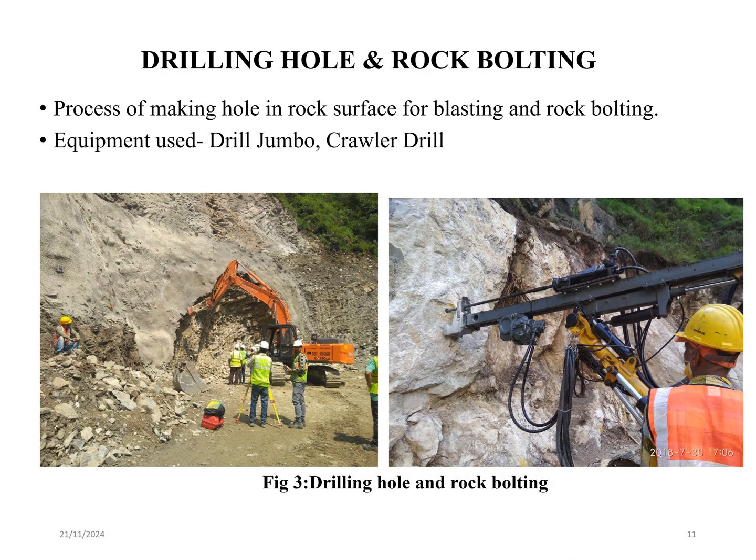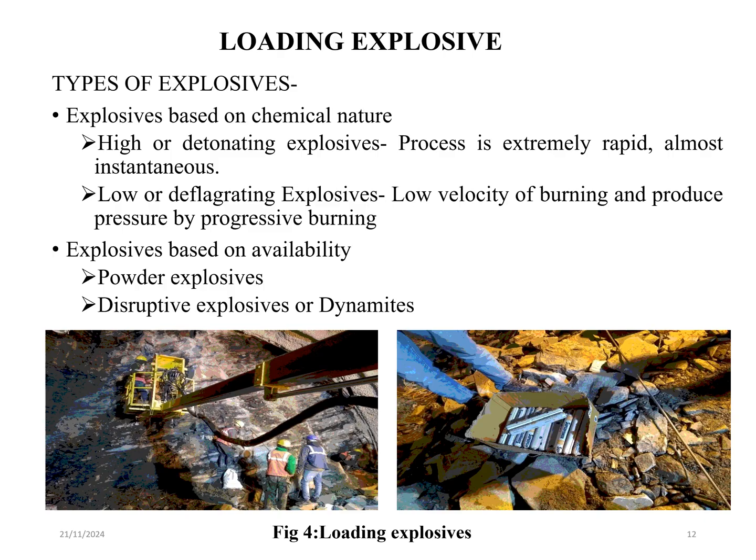Drilling holes and rock bolting. This step involves making holes in the rock surface for blasting and rock bolting. Equipment like drill jumbo and crawler drill are used for this purpose. Rock bolts are inserted into these holes to stabilize the rock and prevent collapses.